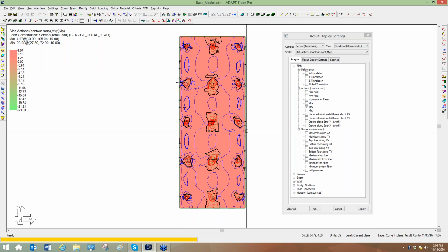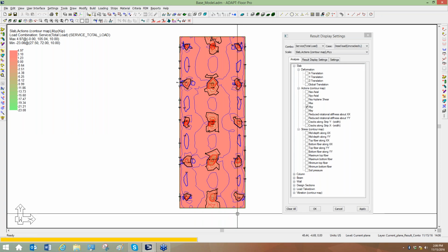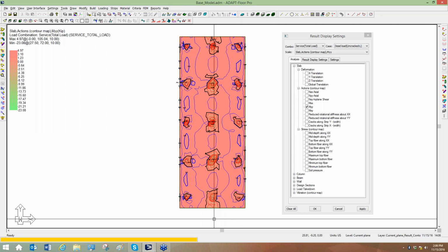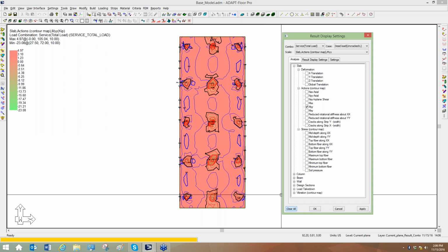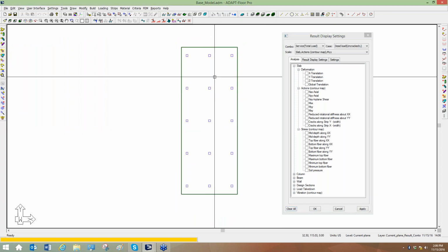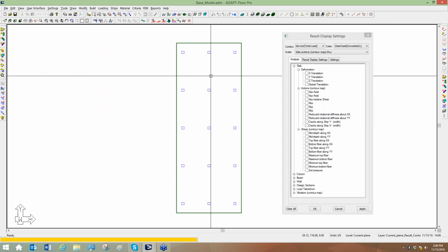we're going to define strips so that we can obtain results both in terms of stress checks and also reinforcement. Now, the question is, how do we define support lines? Well, let me go ahead and clear this contour. There's really two ways to define, I should back up, how do we define design strips? A design strip is really just a tributary. It's a tributary strip or a frame line in the structure.